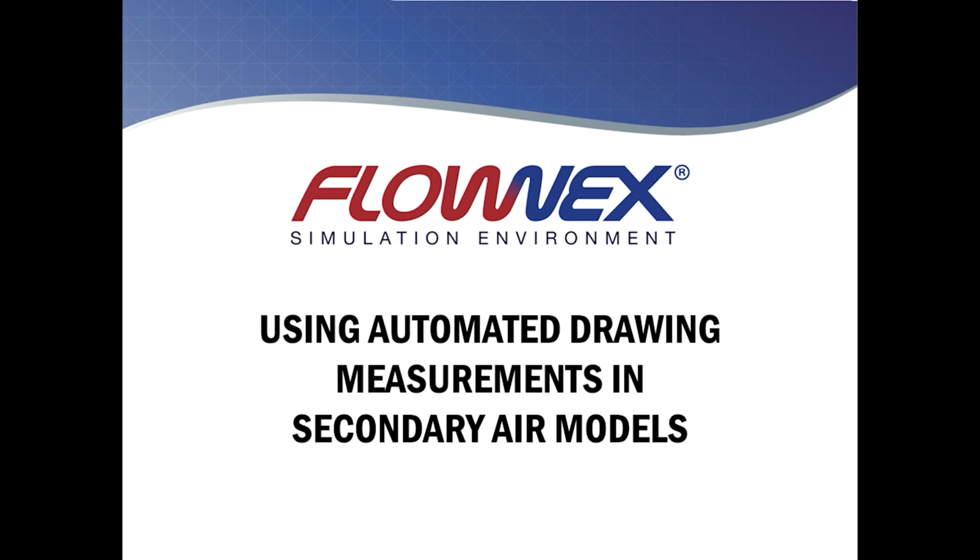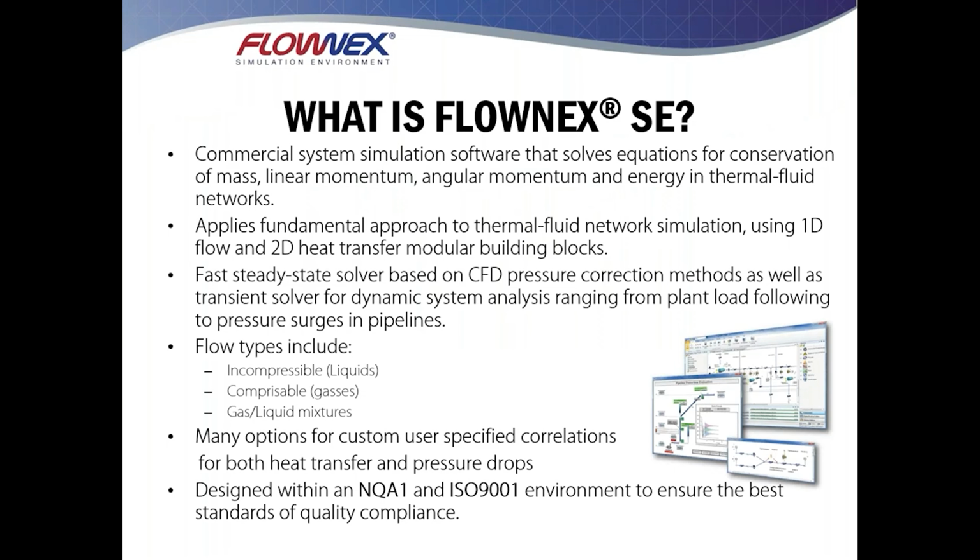Just before we get into the content of the webinar, I'd like to explain what the software is and where it fits into the simulation world, just in case anybody hasn't heard of it. Flownex itself is a commercial simulation software. It's essentially a 1D CFD code of sorts. We use conservation of mass, momentum, and energy, and build a network out of one-dimensional flow and two-dimensional heat transfer components, and then solve that network using a pressure correction method, very similar to how a CFD solver would work.